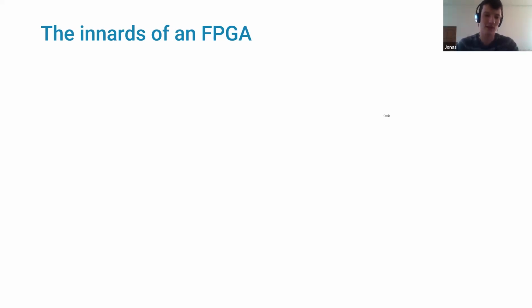And that's a problem that you get into with hardware acceleration. You want to increase the frequency of your clock, which means you want your paths to be very close together so that the electricity has time to go from one part of your chip to the other. If you're working with one specific crossing, there can only be so many signals that go across that crossing, and that affects how fast you can clock your chip. That's a struggle that we've run into on other projects, but not on this one yet, because I am right now running it at low frequencies.